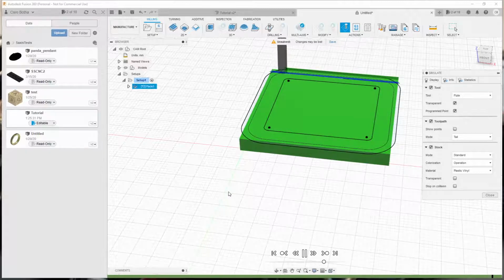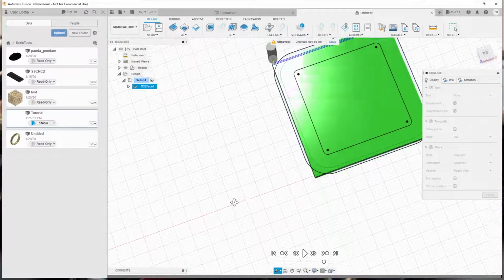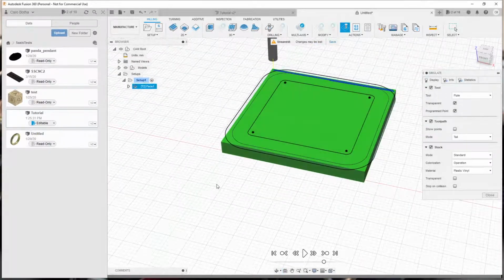And we can see that we're pretty much getting what we wanted. It cut down to the bone and you've got a nice flat surface on it. Okay. Once that's done, we can move on to the next step. I like to cut from the largest cutter towards the smallest cutter, or the largest load-bearing cut to the lowest load-bearing cut. So the one that has the most impact on moving the part, that will be this one.